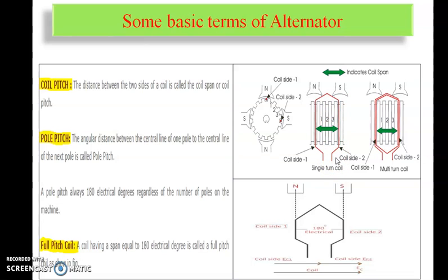ओके, वाउंडिंग कसं केलंय, ह्या पूर्ण मी आर्मेचरच्या स्लॉट मध्ये वायर इन्सर्ट केलेली आहे आणि इथून मी परत ह्या दुसऱ्या स्लॉट मध्ये बाहेर घेतले. म्हणजे फॉर एक्झाम्पल ह्या स्लॉट मधनं मी इन्सर्ट केलं आणि इथून परत मी बाहेर घेतलं. ओके, आणि मी काय सांगितलंय, दिस एंड जे एक एंड आहे, आय कॉल दिस इज द एंड कनेक्शन, while this end I'm going to connect to the commutator segments.